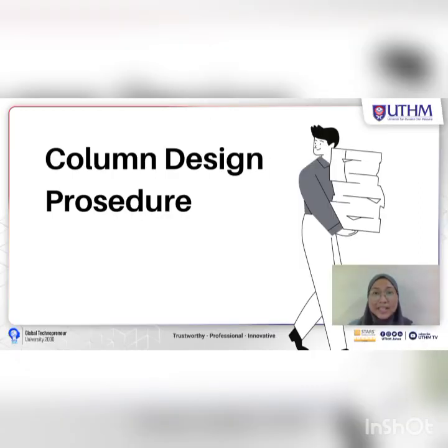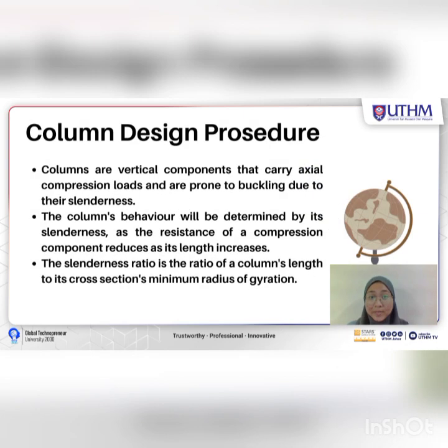Hi, my name is Siti Kasina binti Subarman, and I would like to talk about the column design procedure. Columns are vertical components that carry axial compression load and are prone to buckling due to their slenderness. The column behavior will be determined by its slenderness, as the resistance of a compression component reduces as its length increases.